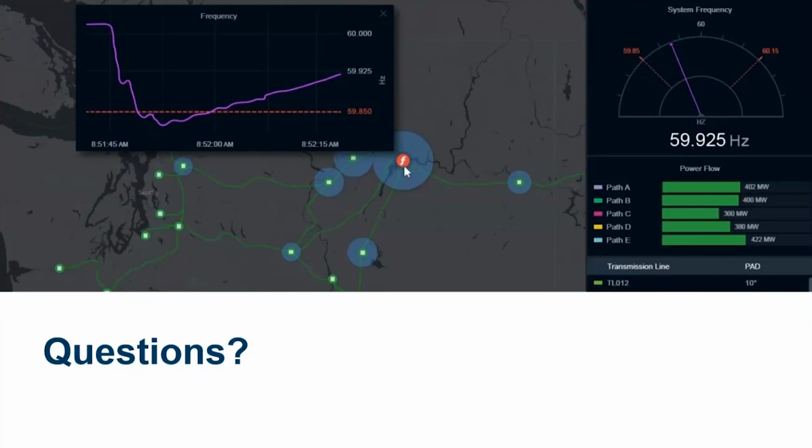Good question. PMU data quality is usually detected and the flag is set at the measurement device. In the IEEE C37.118 stream, there's a data flag for data quality, and we can take that into account within the software. Secondly, we do some calculations within the software to calculate overall availability of a particular signal.